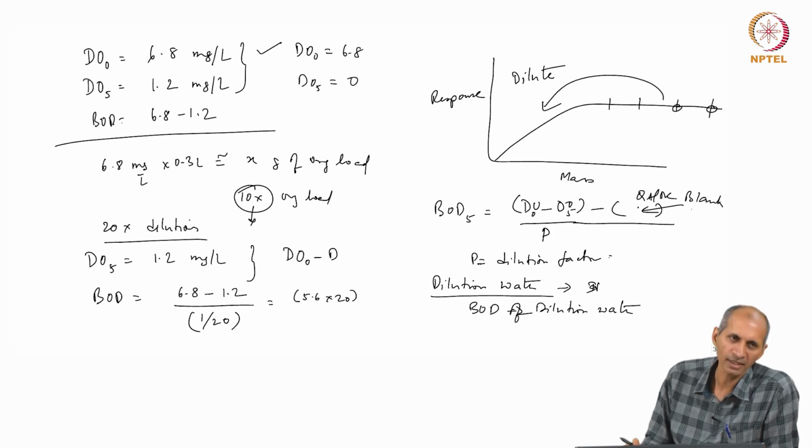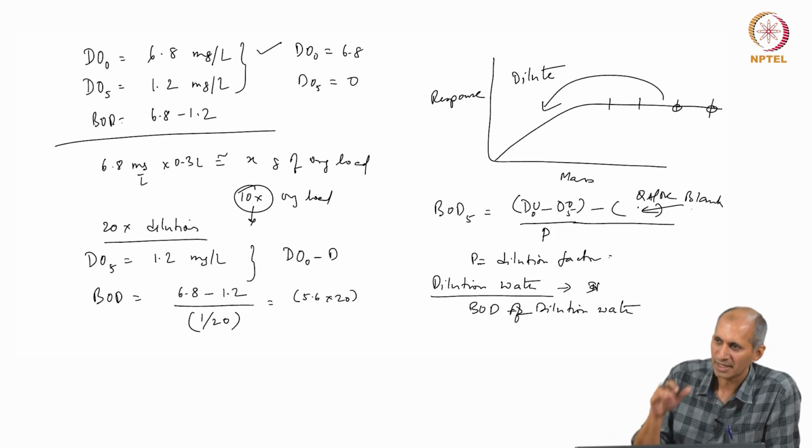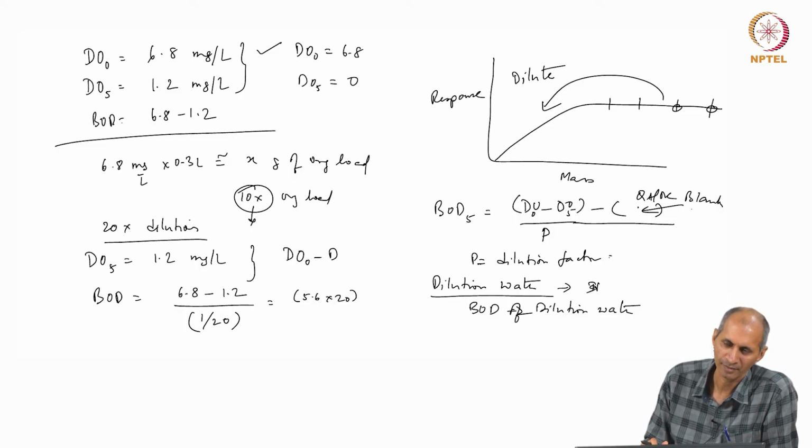If you want to look at leaking of oxygen across, the way we do is we have a standard. What is the standard here? What could be a standard? Oxygen is the standard. We are measuring oxygen. So, you have to calibrate the instrument using oxygen.